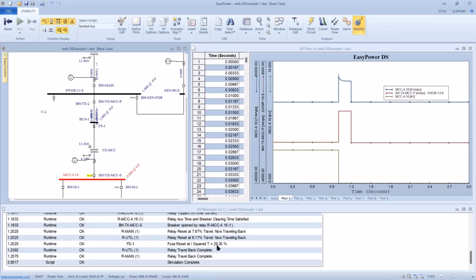So the point I'm trying to make is on any overcurrent fault, we're going to have some amount of fuse protection decreased because this doesn't reset. I mean, it doesn't heal the fuse. So when you have a fault in a system, you need to replace all 3 fuses that are in series with that particular fault, which I find interesting.